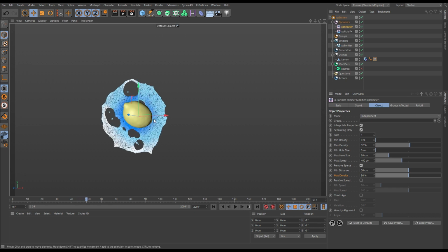So in this scene, this isn't the correct tool for us. By having removed sparse, we're actually creating sheet particles within this sheet here, and we're deleting some of those within that sheet, and we're getting this what looks like flickering, and that's not what we want, and it's not what this function is intended for. So only use it if you're experiencing some sheeting appearing outside your main simulation sheet body, and you want to get rid of those.